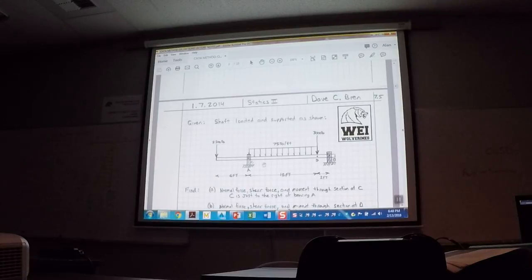And the interesting thing about that is what's happening, say, at that collar. If I take a section at C, that's actually an important spot. I've got to make sure I have a collar right here that can handle the load being applied to it. Notice that if I did take a section at C, I would have this 2,500 pounds pushing down on the outside edge of that. Think of this as just like a cantilever beam, by the way, this little bit cantilevered out. And then think about this as a beam between two sides of basically a bridge, a beam spanning.